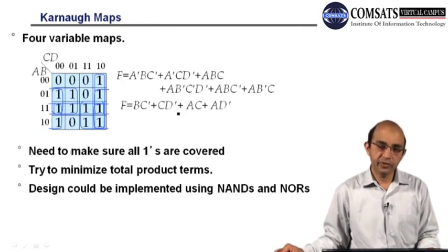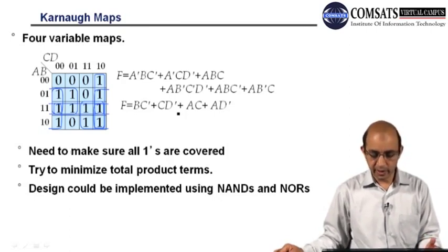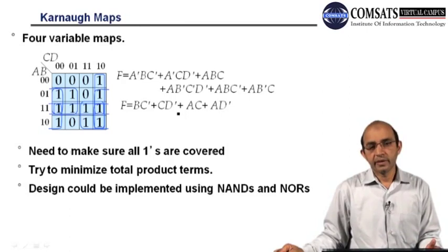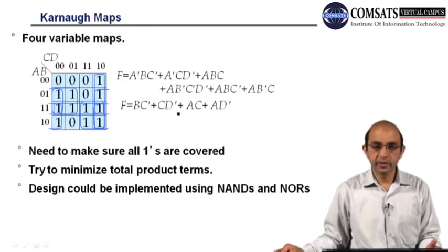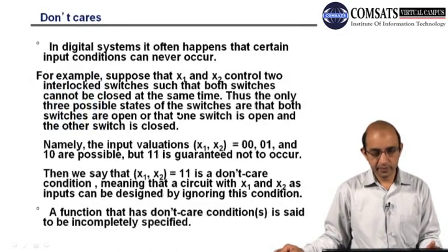From the design point of view, you can use NAND gates or NOR gates, or you can use OR and NOT, it's your choice. But NAND and NOR are universal gates, and they have some good characteristics which favor digital design. That's why we try to implement the final Boolean expression by using NANDs and NORs.